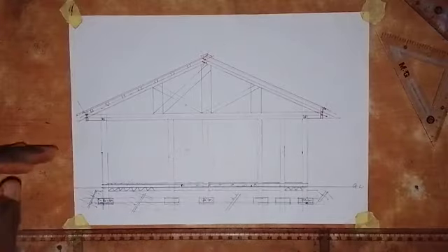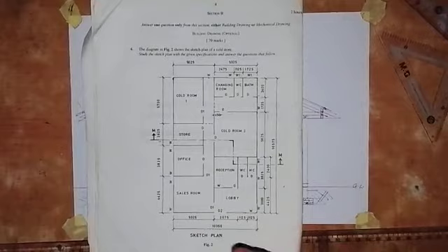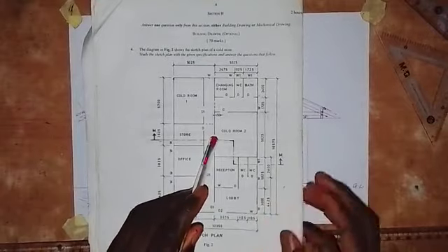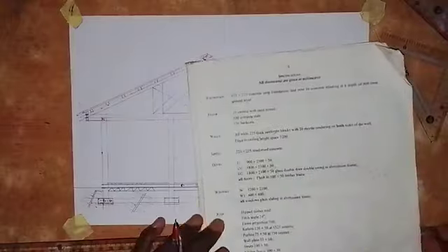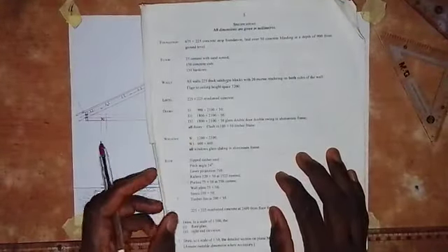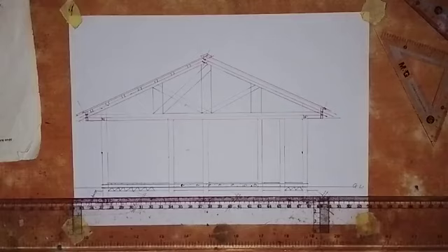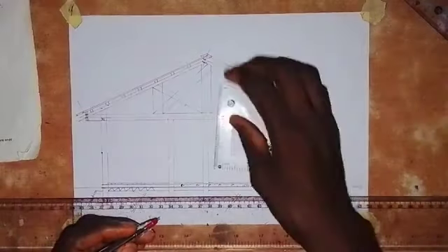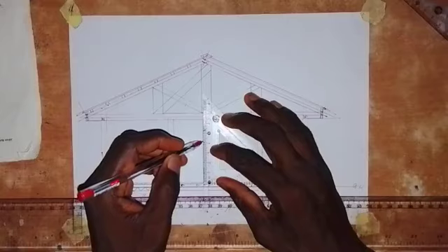All right, so now let's work within here. So let's quickly work within here. So what do we have within this? So let's start with the door. So there's a door that we have here in this wall. We have a door in this wall, the third one here. If we move from this side, we have a door here. So the height of this door is 2100. So that's going to give us 42 millimeters. So we come here and take a measurement of 42 millimeters up. So here we have 42 millimeters.